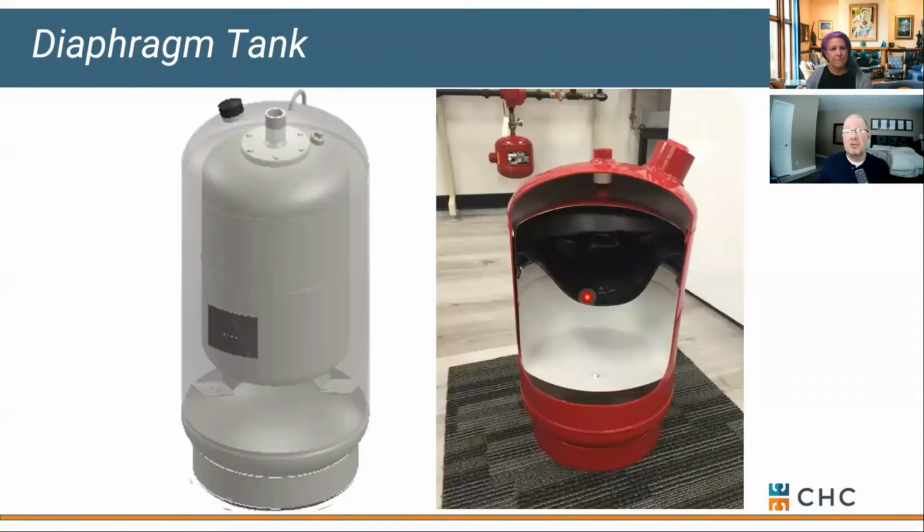Now, what a lot of manufacturers do with diaphragm tanks, they will put a non-code or residential tank inside an ASME vessel. Clearly, there's no way to service this tank. If this diaphragm fails or ruptures, it's a pull and replace. There's no way to access it.